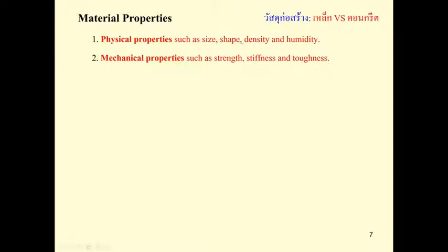And also, you got to do some testing for the strength and the stiffness and the toughness of the steel. The industrial standard will specify the strength and the stiffness of the steel, and if you test this and you get lower than the strength and the stiffness, again you should reject that material back to the supplier.